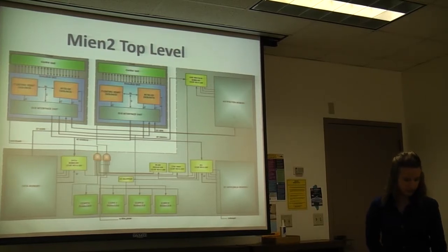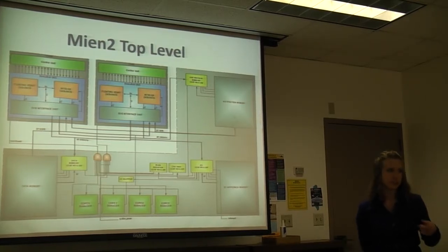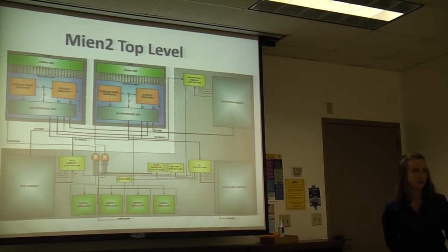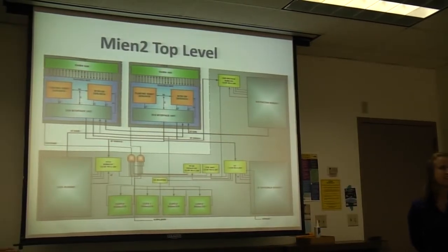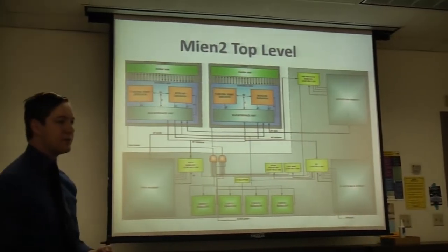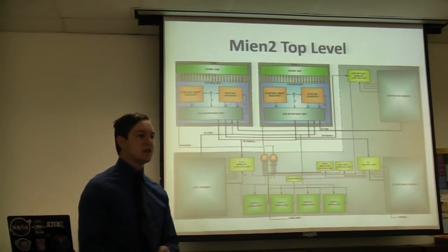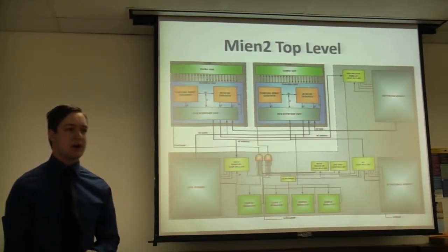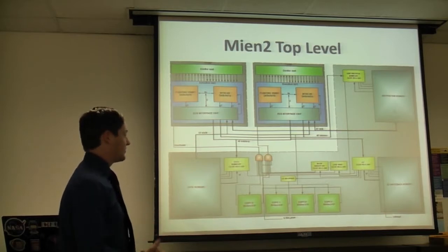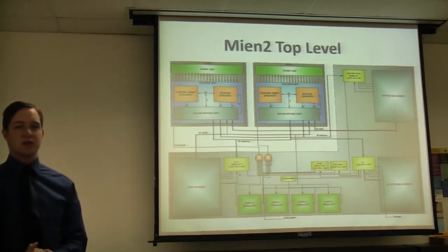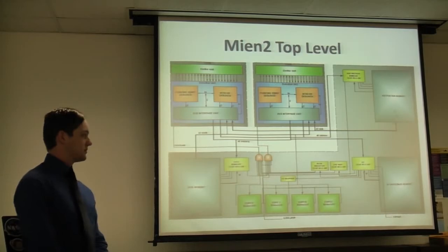It's just which cycle of the fetch, decode, execute phase they are on that is off. But they're synchronous to the same clock, right? Yes. With pipelining and caching, the cores can be synchronized, but without that, they both have to wait for data memory and instruction memory and IO memory.